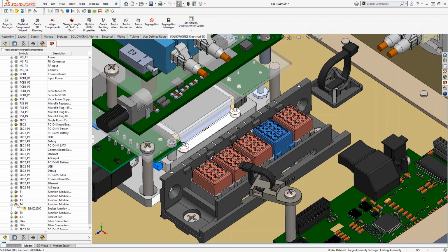All right. So each part will have a little checkbox next to it. In this case here, I do have the ability to insert, which means, if you remember that key factor I showed before, that slide with all the manufacturer part information, if I select insert, it's going to go to that particular file. It's going to look to that field where I have a solid part in the directory for that field, and it's going to pull that up into my assembly here and allow me to mate it as necessary.